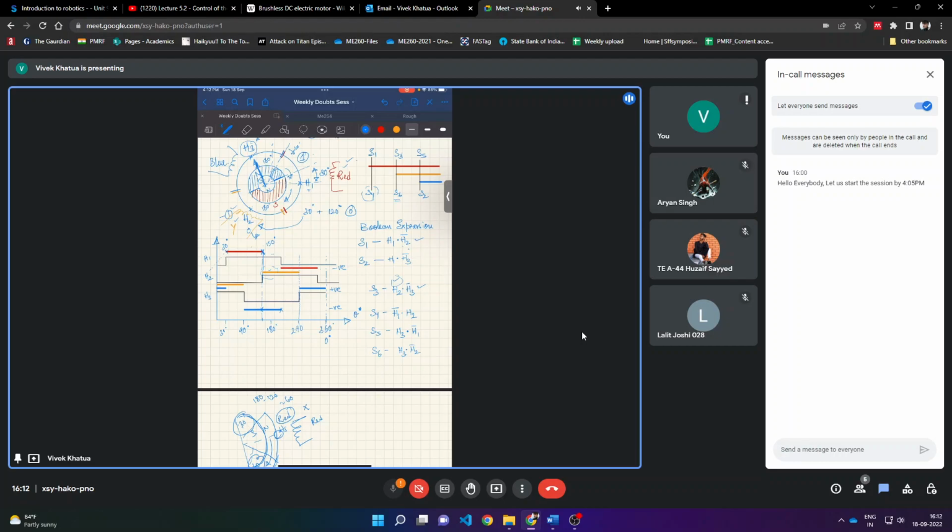So here you can see the H2 will be high in this particular region, right? And H3 bar will make it stop at 270 degrees. So like that you will get from 150 to 270, where yellow is positive, 30 degrees to 150, where red is positive, and then we look at S5.